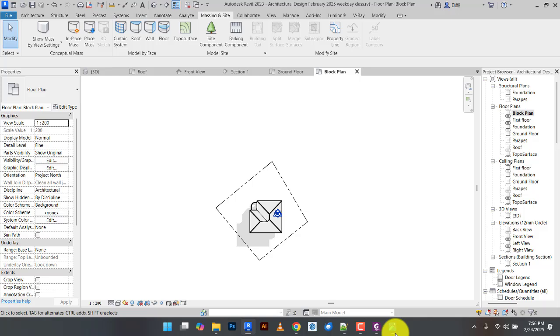When we have survey data, they can give the survey data of the land, the actual survey data, where you can see the contours and all that. Revit has the functionality for you to import that survey data, then generate that exact land with the nature, everything on it. You bring it from Excel, take that value, and give it the exact nature of the land.